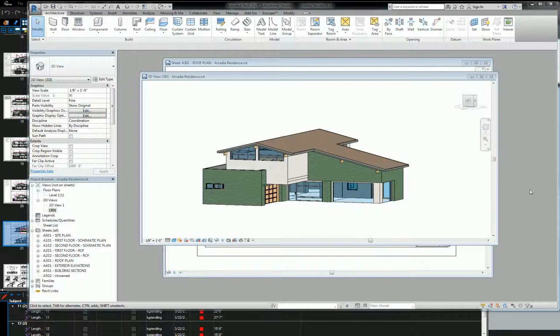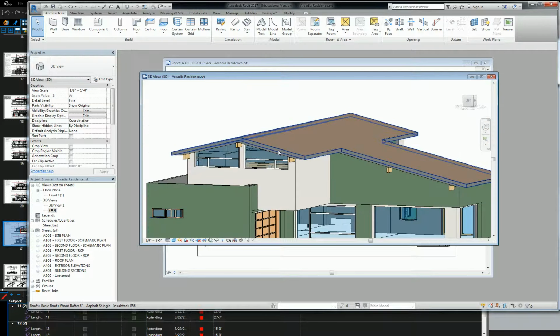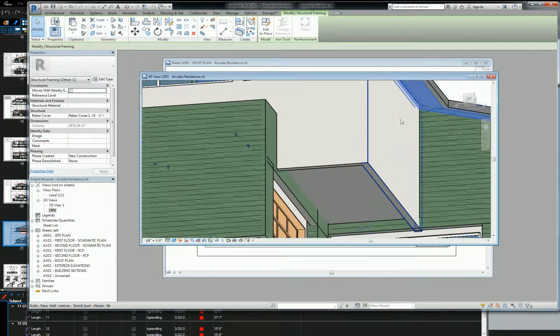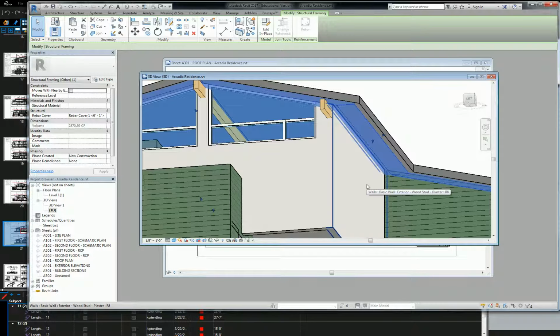All right, to get a little bit more detailed about structure, I'm going to show you guys just some basics about how to put in some structural families. I did show you how to already put in beams, but you don't yet know how to do a joist framing system. Right now all of our assemblies are just these masses, representing the striation or the cadence of joists that's going across the building.